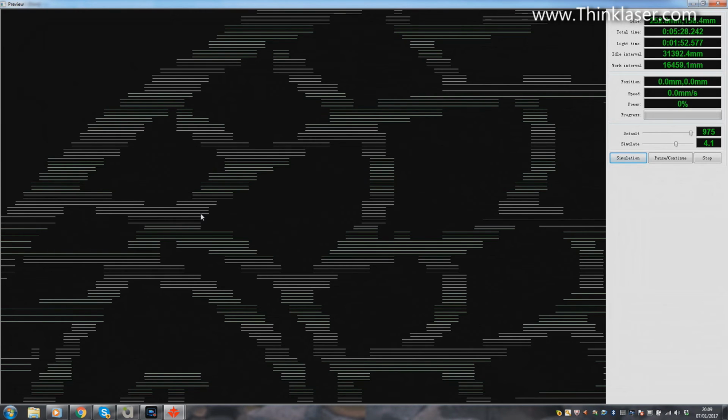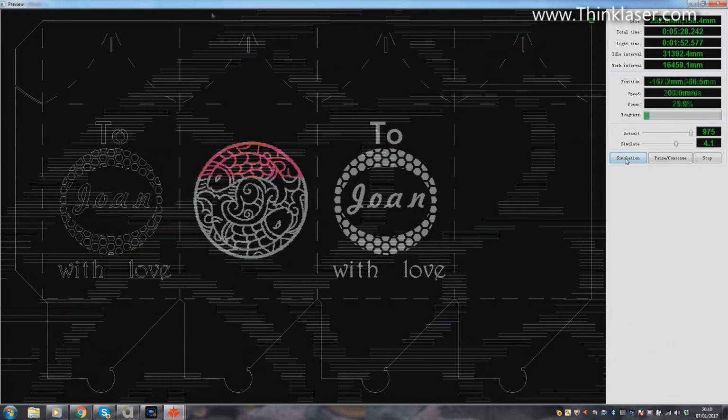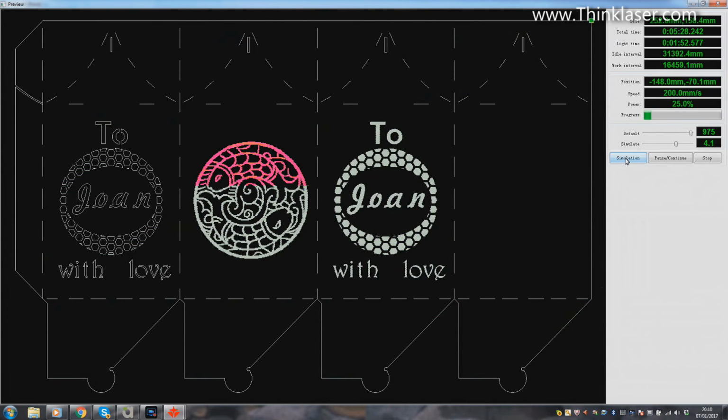So the only way that it can generate this graphic is if it scans across, stops, starts, stops, starts, stops, and it goes backwards and forwards in scanning mode. So because these scans are on different layers, they are done separately. If they're on the same layer, then both of those scans would take place simultaneously in one single scan line.